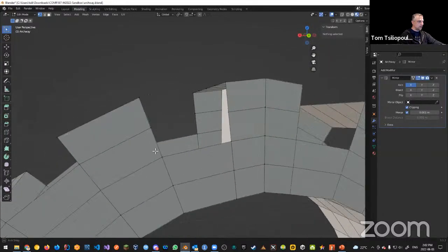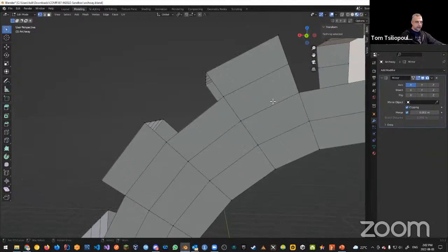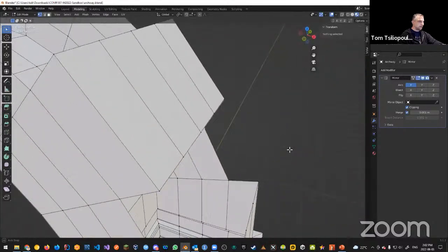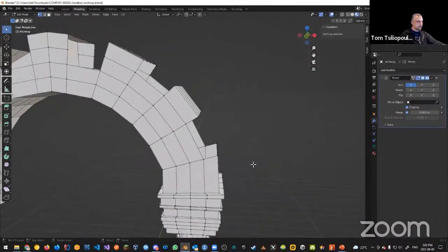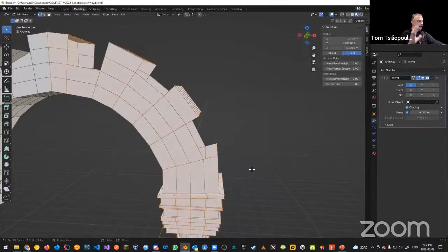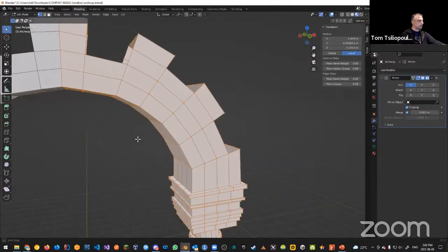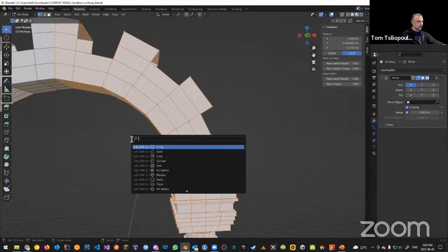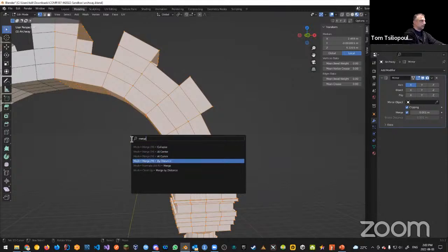I don't see that there's a lot more. And then I'm going to do what you said, one, which is get rid of duplicate geometry by distance, because there's going to be issues. All right. So again, I'll select the entire model now, right? The entire model that I have. Remember, it's still mirrored left and right side. And I want to hit space and go merge by distance.